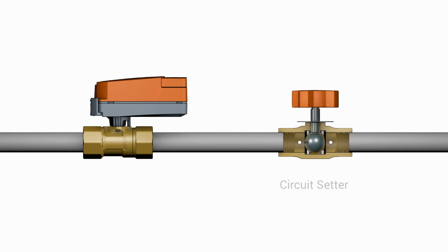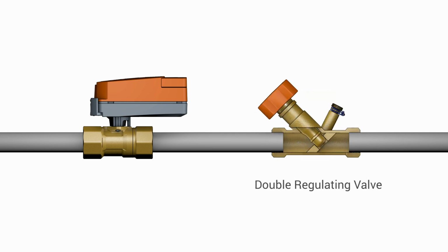These valves need to be purchased, installed, and adjusted several times to ensure each control valve gets its fair share of water. Sadly, even though they're balanced, anytime they're not in their design position, they're not working as intended, often resulting in too much or too little flow. This complex balancing process is easily nullified by any changes or alteration elsewhere in the building. Even the slightest change elsewhere in the building changes the pressure profile of the valve, completely nullifying the balancing process that's gone before it.